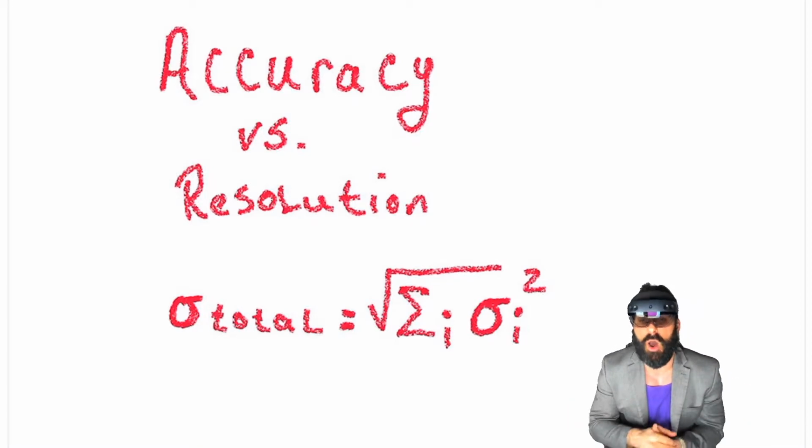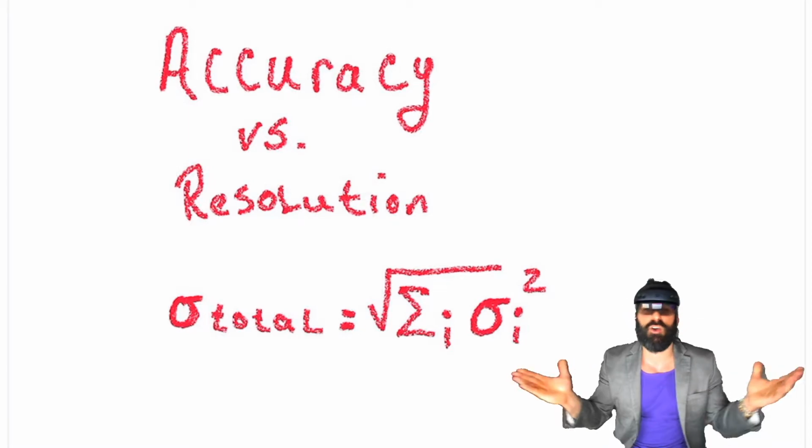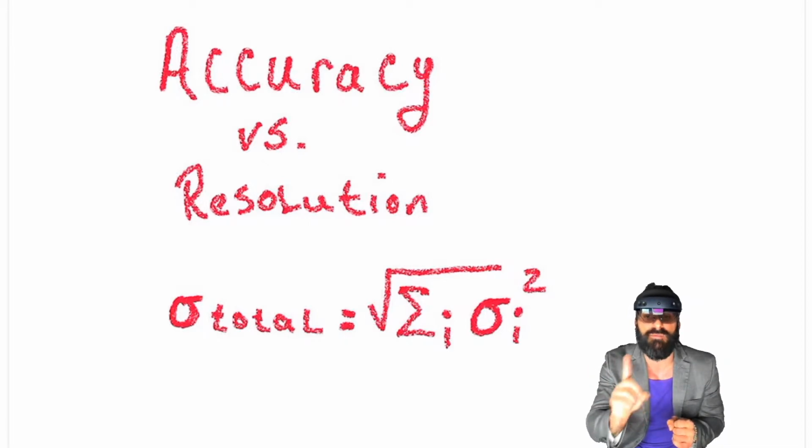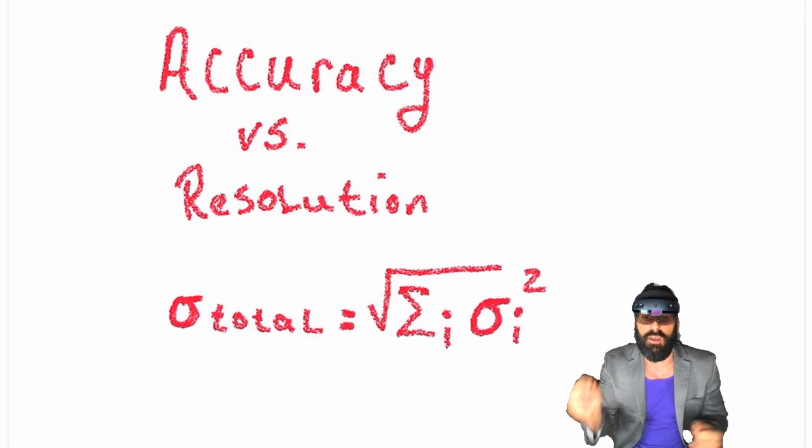But let's look at the quantization error. Now in a theoretical world, a perfect ADC with an input analog voltage measurement should be represented by a unique digital code accurate to an infinite number of digits. But in the real world, ADCs have small, finite gaps that exist between a digital number and a consecutive digital number. And this amount depends on the smallest quantum value that the ADC can resolve. Now in the case of the 12-bit analog to digital converter covering a 10-volt range, that quantum value is, as we showed previously, 2.44 millivolts, the least significant bit.